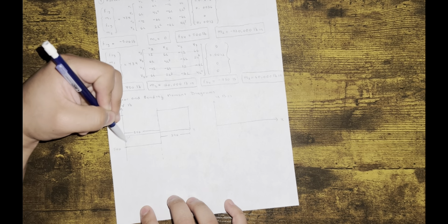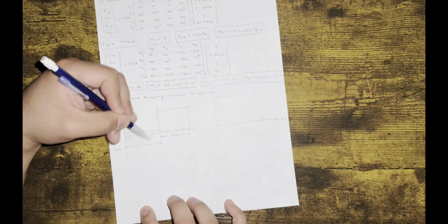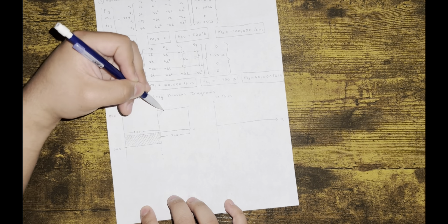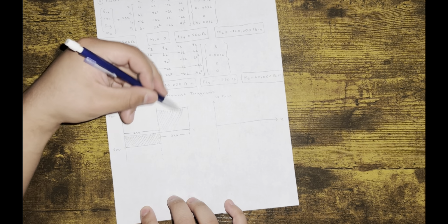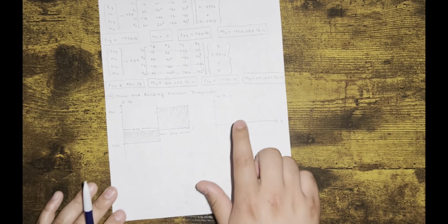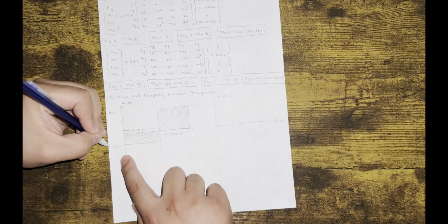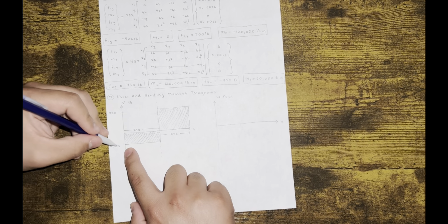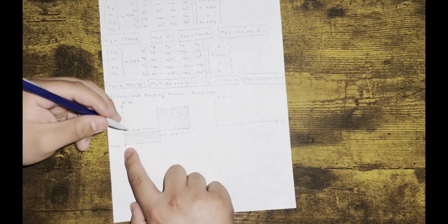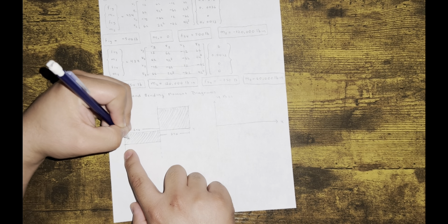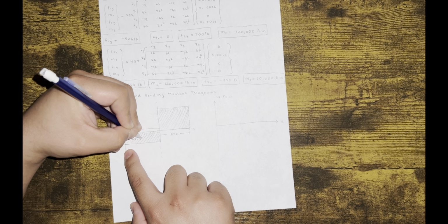So let's go ahead and shade the area, right? Just to make it look nice. You don't have to, but whatever. I like to be creative with it. Okay, now to get the shear, the bending, use this to get that. In this case, look, we have a negative 500, okay? Negative 500 times 240 will give you negative 120,000 pounds.